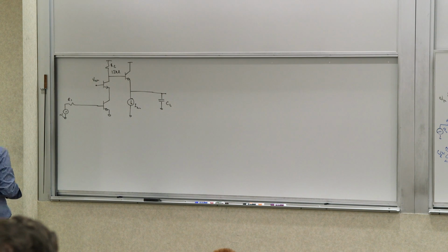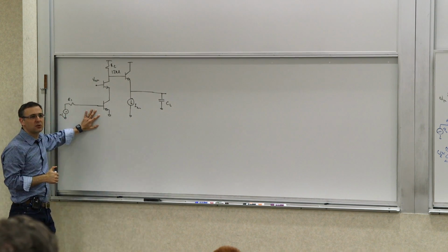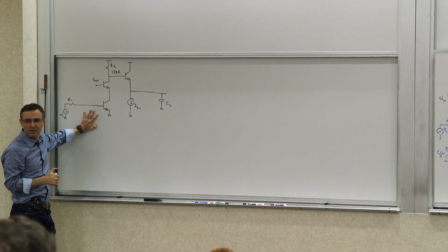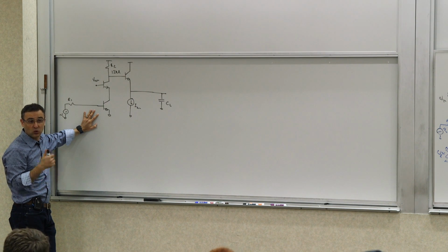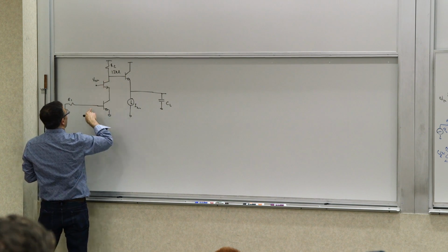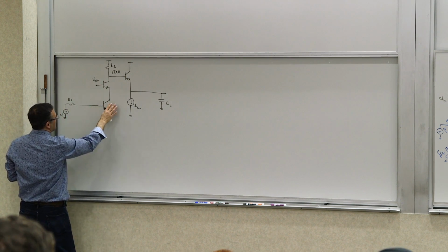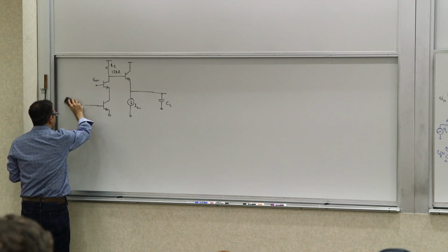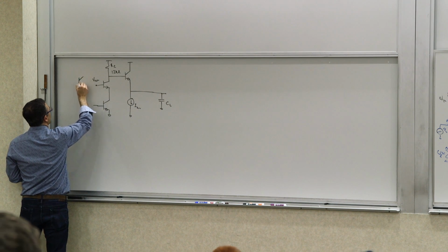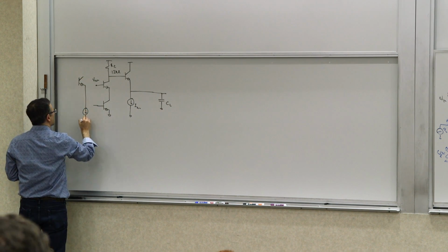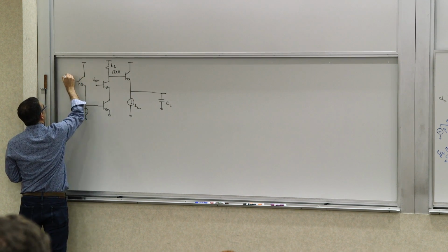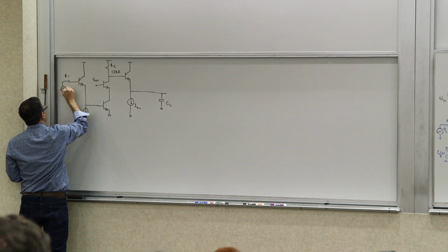And we also saw that we are losing some gain in the input voltage divider. We didn't really do that next step, but we could add an extra buffer in the input to reduce that loss. So the next step in that design, if you wanted to enhance it, is to say, okay, I can recover some of my gain here because I really don't need to have that. So let's take that conceptual design one step further, and then let's say you have also a follower here. Conceptually, that's driven by some R1 source resistance and Vn.